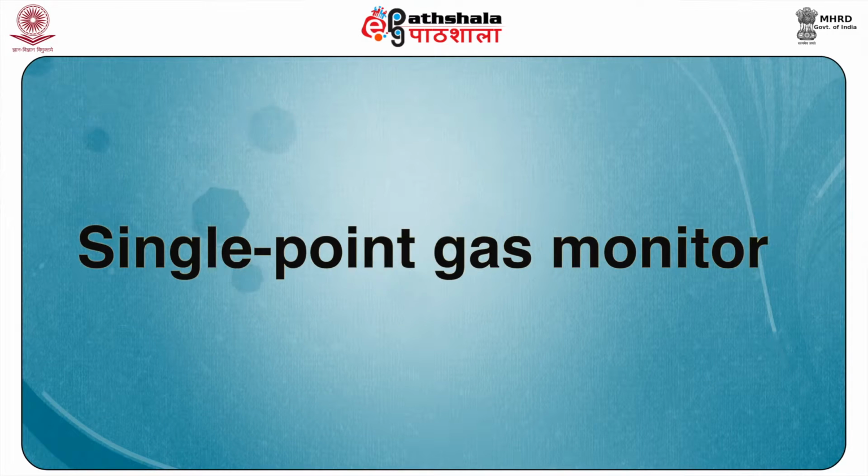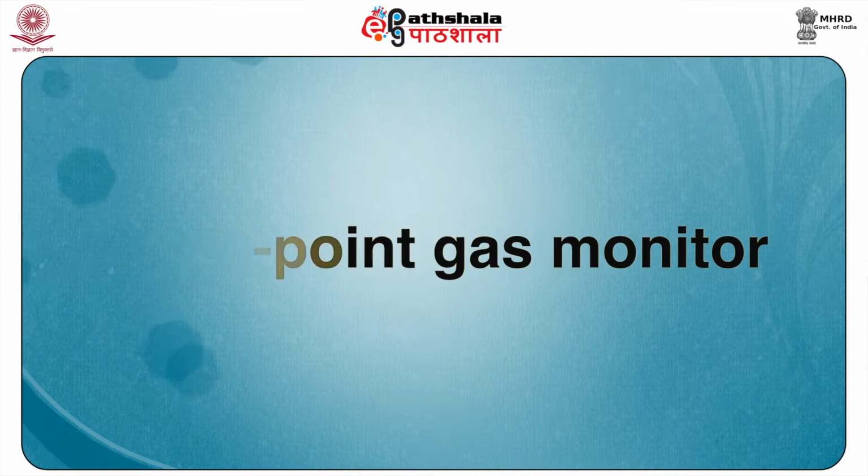There is another device which is known as single point gas monitor, and there are certain features and characteristics of this device. It is a compact, pocket sized, single gas microprocessor controlled monitor and used to continuously detect and display gas concentrations on an easy to read large digital display. It is required for potential gas leak areas.